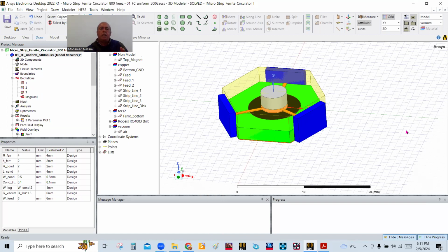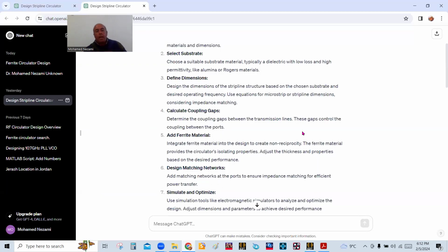You've got the line that feeds the stripline or Microstrip line, so you've got the width, the thickness of the brass or the printed line, and then the diameter and height of the ferrite, the height of the substrate. So there is not a whole lot of parameters to design, but we have the equations. You throw them in there, extract some dimensions, build it in the model, and see what you get, and then iterate from there before you do machining.